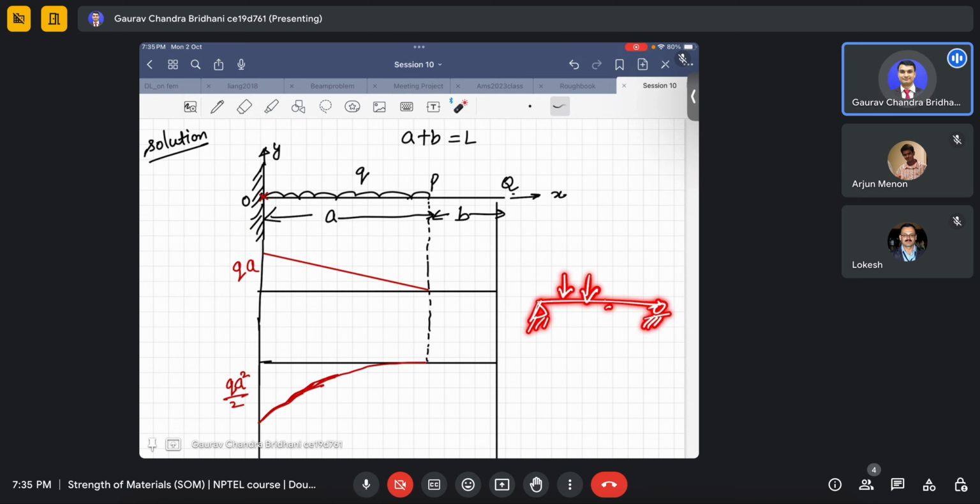So basically, you go with that specific parenthesis thing. The professor also showed it, x minus a kind of thing. So you use that, or the other way is you can find the MB value for each region. Like you have a roller here, you have a loading here, so you write the MB for here, and the MB for here, and then you define your deflection for this region and this region. But when you integrate, you have to come up with the condition that at this point of loading, the deflection will be continuous.